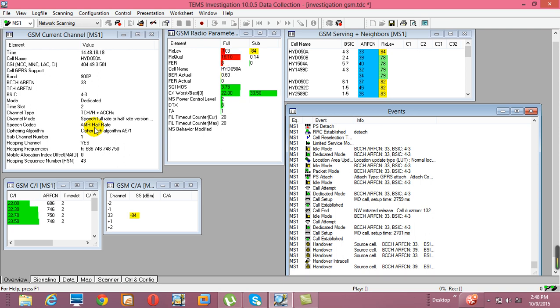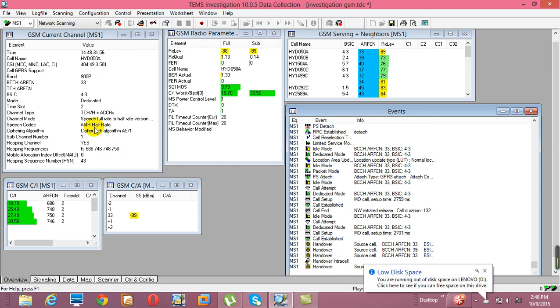This adaptive multi-rate is a kind of speech codec which can add some extra redundancy bits to the original bits. If any data is getting lost, it can be recovered with that, so we reduce some data loss. Depending upon the channel, the redundancy is added. If we have the full rate, there is more redundancy. If we have the half rate, we have less redundancy. Okay, clear?